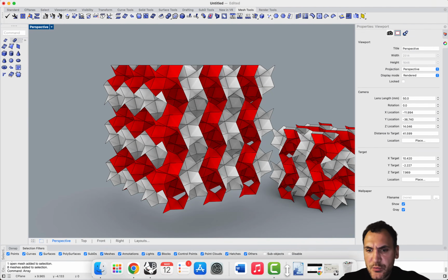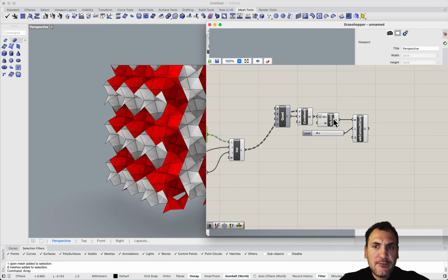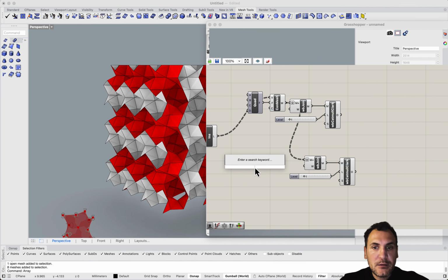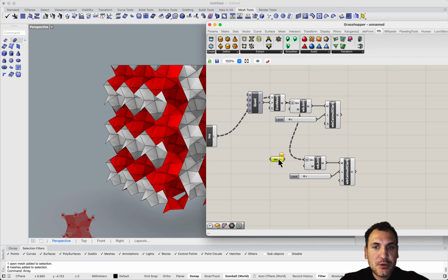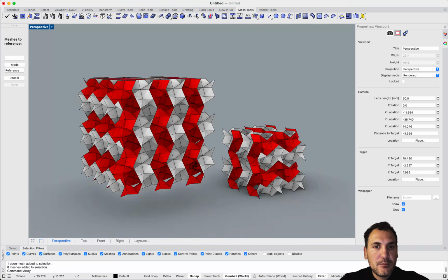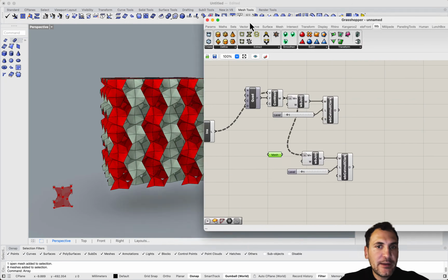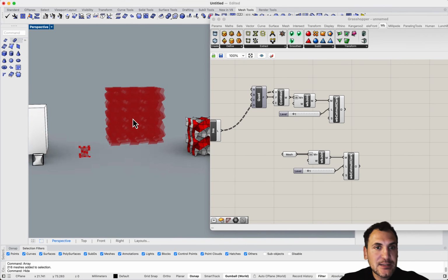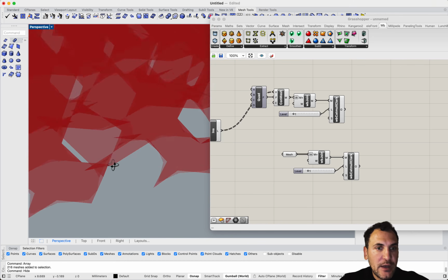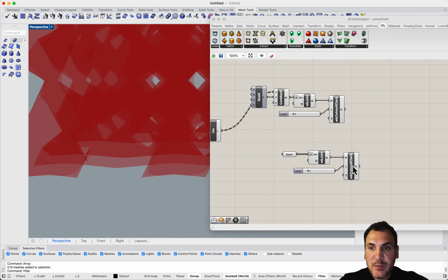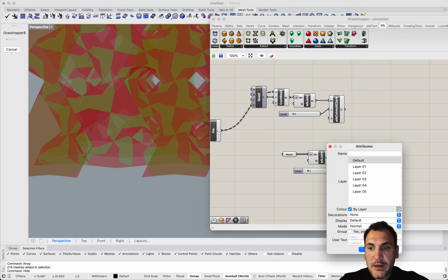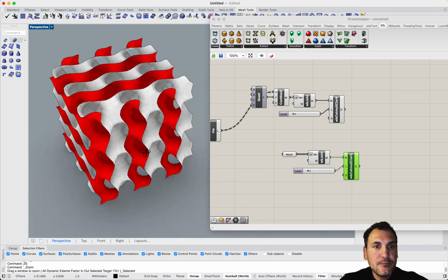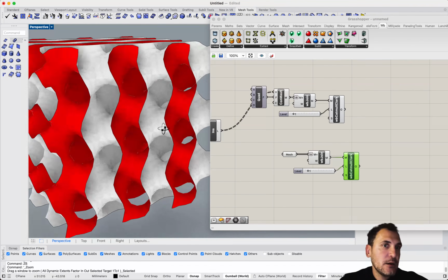And this should work the same way for our subdivision. So if you just make a copy here, make another mesh, and put these in, let's hope the vertices are actually touching each other, because they need to join. If you have discontinuity, this may not work. And I'm going to bake it. What you can see now is a subdivided construction, right?